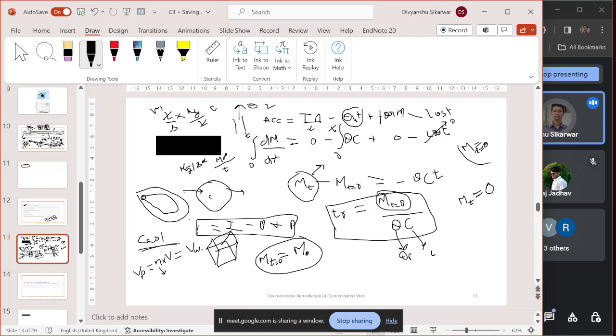If we know the volume of water, and the concentration of contaminant in water, and multiply the two, because concentration will be milligrams per liter and volume will be in liters, the liter will cancel out and we will get mg.